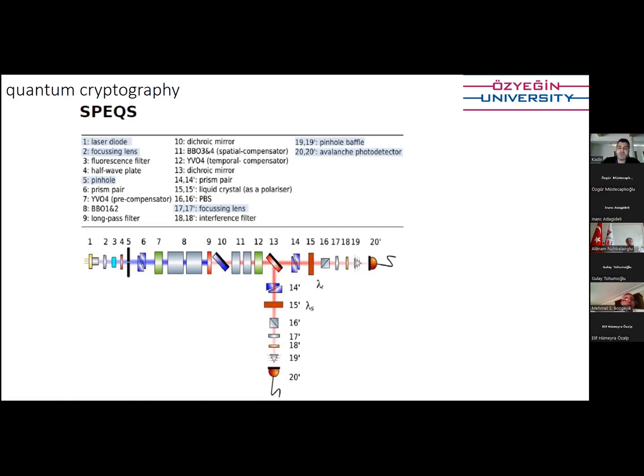So of course, the main candidate for such a purpose is titanium. But the problem with titanium is, when you machine it, and then cut it with the knife, after a while it just changes shape. That's called stress relief. When you're cutting the material on the CNC machine, you're applying some stress. Therefore, you need to relieve that stress so that after you send it to the satellite, it doesn't change its dimensions.